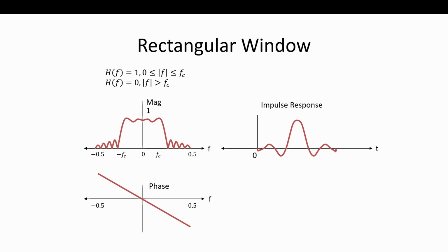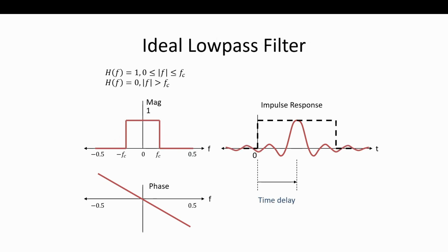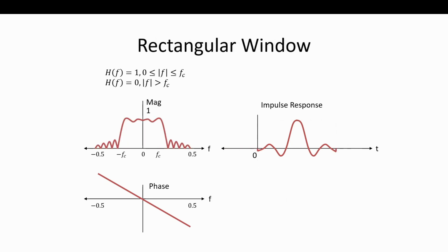So the rectangular window, that's what you saw. It's called a rectangular window. We just decide to truncate. That's it. We multiplied it in time with a rectangle. So we're going to see lots of these rectangle pulses and lots of sinc functions, right? You see that coming up again and again. So by doing that, that's what happened to our frequency response. See, we're getting passband ripple and stopband ripple because of that very thing.